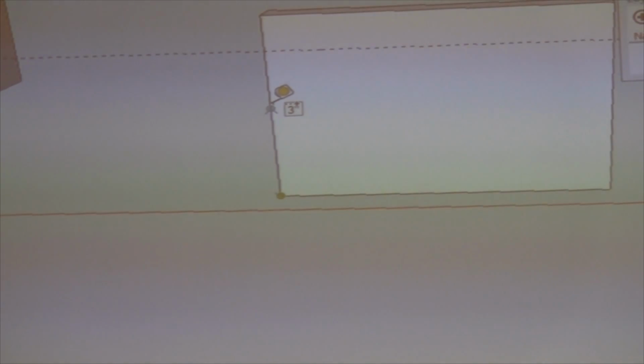If you come on an end point like this, and you move up, you will make a mark. I'm going to put a mark right there at the 4 inch mark. But you don't see the line. You see a little dot, a little plus sign. You see that? Yeah. But that's all you get. And the reason is because the line is there, but it's against this line. And because it's against another line, the tool does not make a continuous dotted line. It only makes a tick mark.